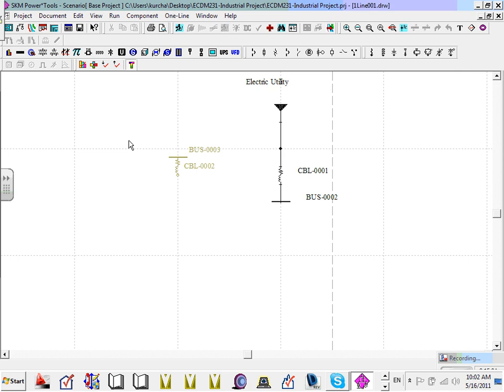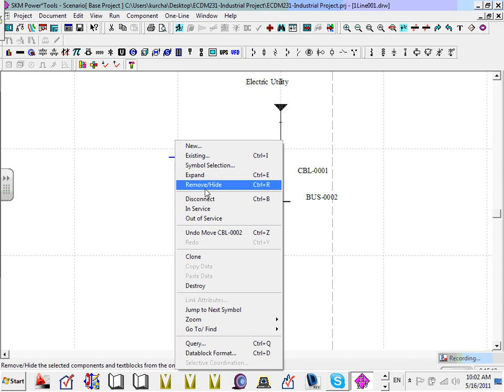The second thing: if I want to copy something, they call it clone with area. So look at the stuff that I did right here, guys. I'm going to destroy it. So I'm going to grab and highlight them. See, they become blue. Right click on it. Do you see the word destroy? Do you see remove? Don't remove. Remove will remove it from this window but keep it in the database. So that's the one I did just as an example. I'm going to go ahead and destroy. Can you guys see what clone is? Clone copies everything with data. Copy, very powerful.